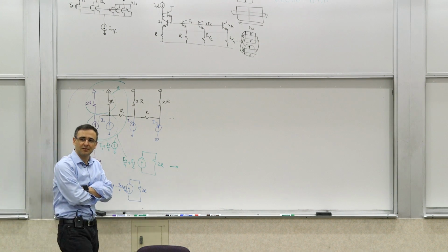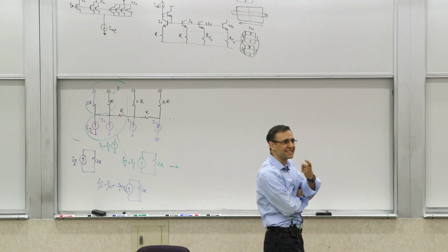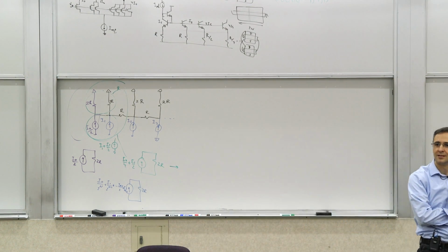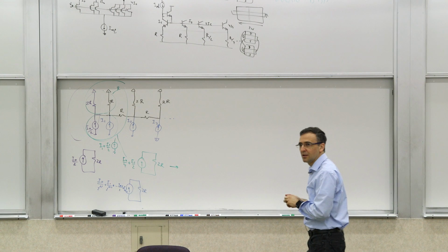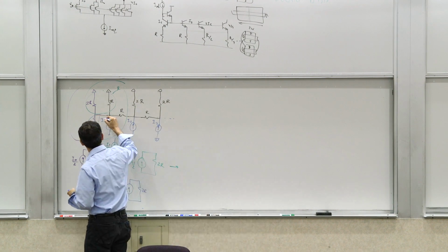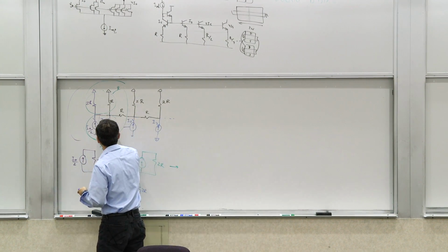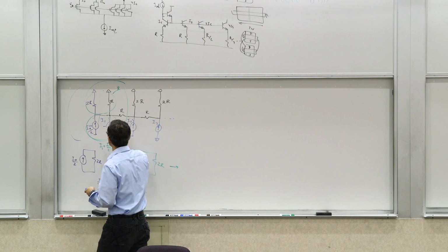So you can see that this R-2R ladder essentially scales the current sources for you. You can have current sources that are similar in magnitude, and you can turn them on and off. If you really wanted to, you can just put switches here or actively turn them on through a control voltage. That's probably better.